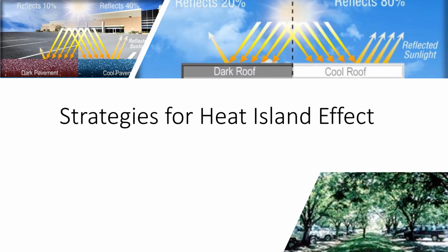Roof strategies include using a cool roof or a high reflectance roof. You need to use roofing materials that have a specific minimum SRI, which differs whether it's a low-sloped roof or a steep-sloped roof. A low-sloped roof must have an initial SRI of 82, with a 3-year aged SRI of 64.